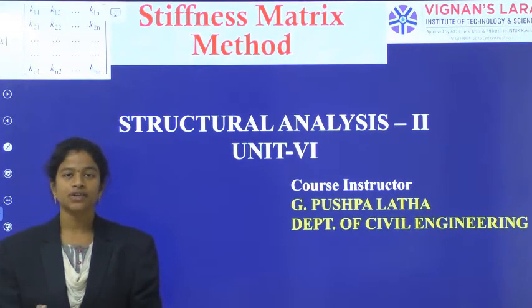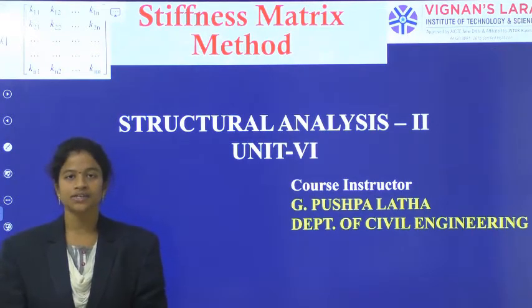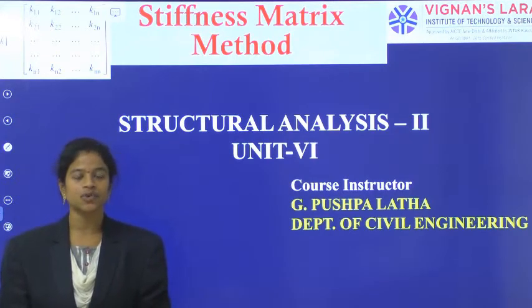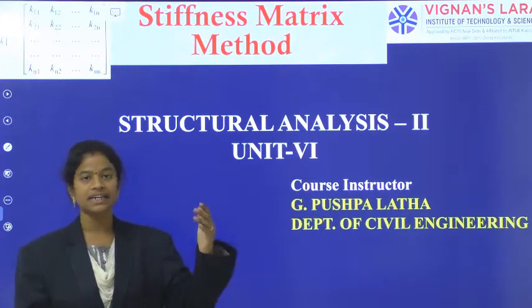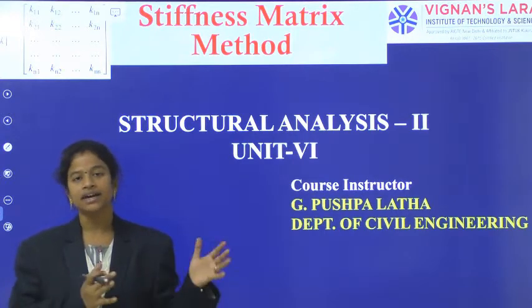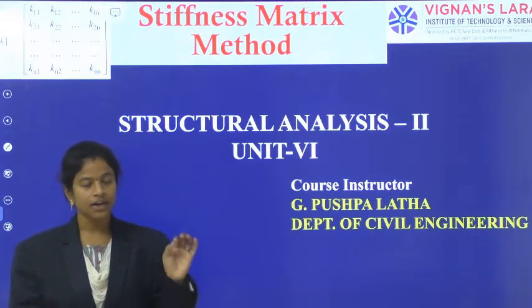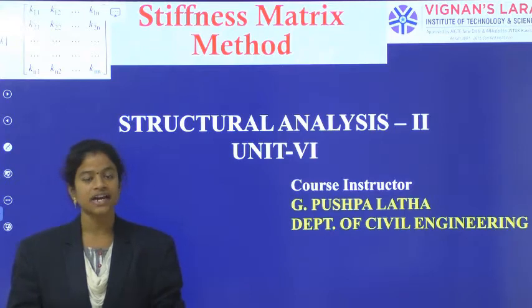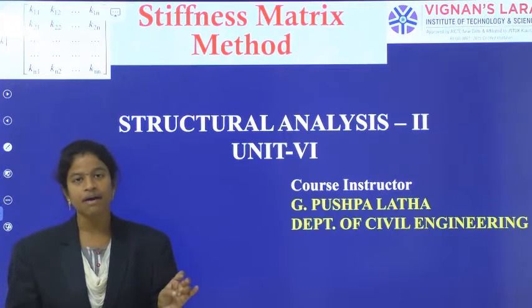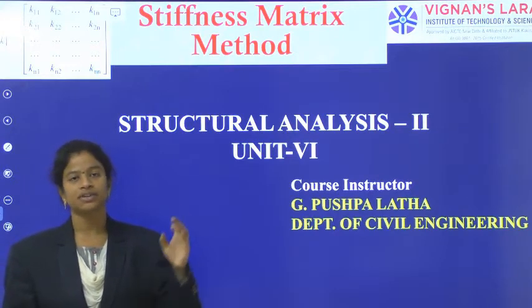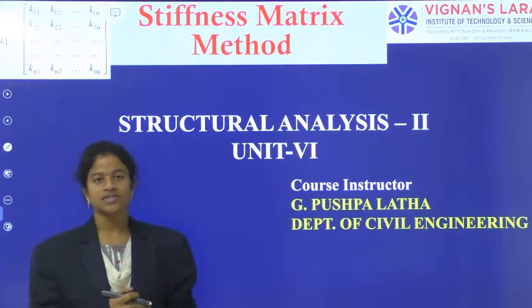In the previous classes we went into the matrix methods of structural analysis, and we came to two methods. The first one is the flexibility matrix method and the next one is the stiffness matrix method. Each individually has its own name and its own method of calculation. In the flexibility matrix method, as the name itself says, we use the flexibility matrix, and the forces are the main unknowns, and we use compatibility equations. That's why it is called the force method, flexibility matrix method or compatibility equation method. There the main unknowns are the forces.